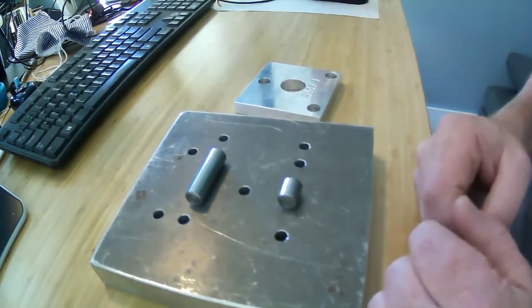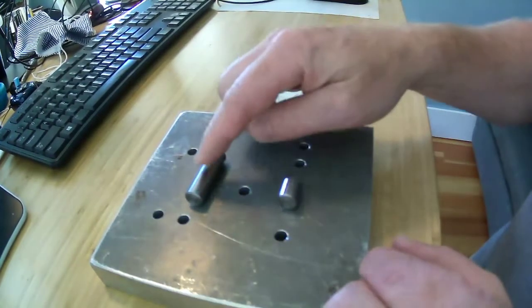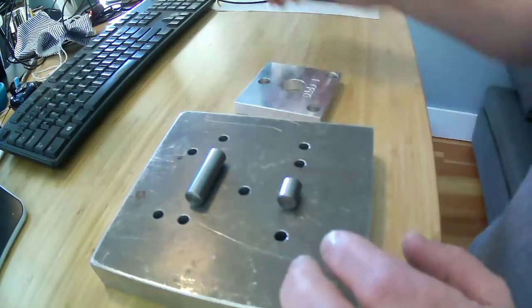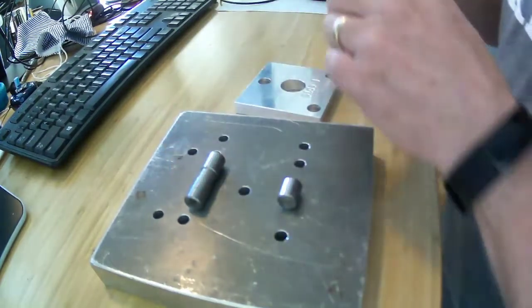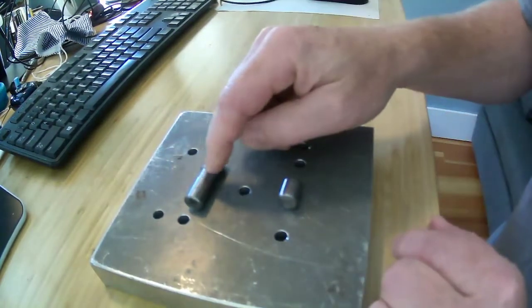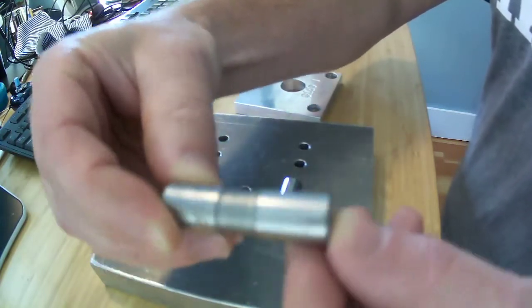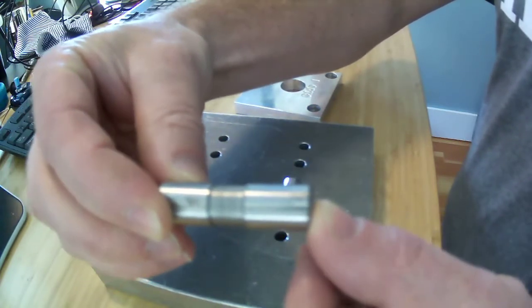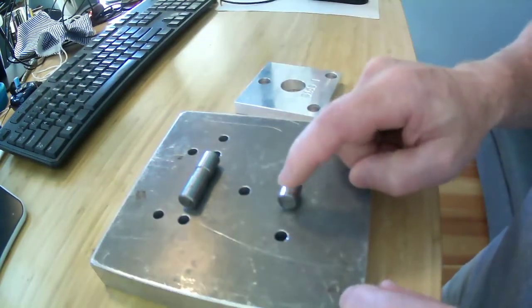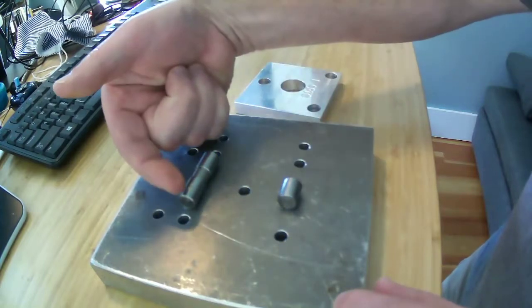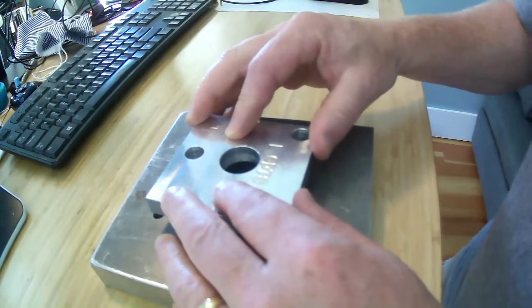Okay, how could I make it more deterministic? Well, I could use two little dowel pins back here instead of this one. We could use individual dowel pins, or we can use one big dowel pin and do what we call relieve it, where we put a slot in it. Let me hold that up so the camera can see. That's had a smaller diameter machined in this part of it. So now I know that it's going to contact along this length and along this little length and along that length. So I've improved determinism even more.